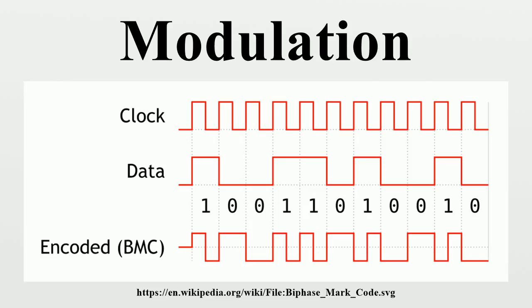Perform digital to analog conversion of the I and Q signals. Generate a high-frequency sine carrier waveform, and perhaps also a cosine quadrature component. Carry out the modulation, for example by multiplying the sine and cosine waveform with the I and Q signals, resulting in the equivalent low-pass signal being frequency shifted to the modulated passband signal or RF signal.